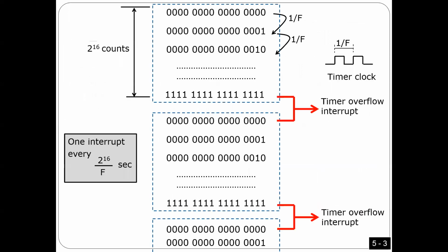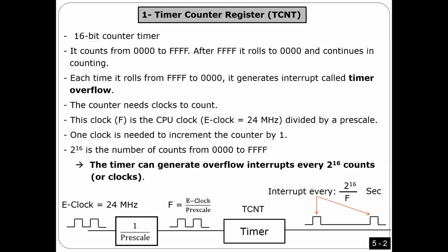As I told you guys, here we have only one counter, a 16-bit counter. How does this counter work? Look at the English name, it's called counter because it's counting, right? Otherwise, it wouldn't be a counter. So the idea of the counter is, it's a 16-bit circuit, and this circuit should have a clock here and work by that clock. Every cycle, the counter is going to increment by 1, right?